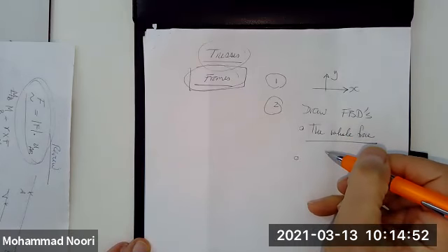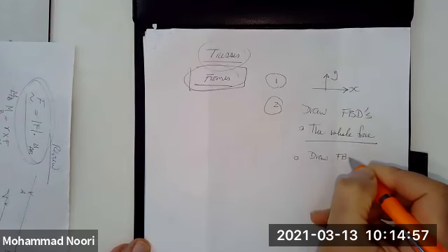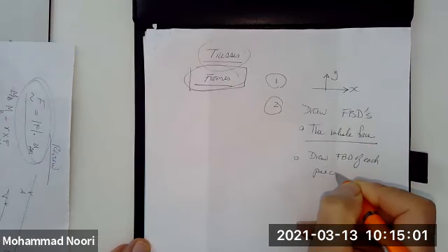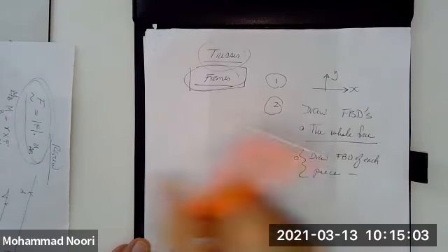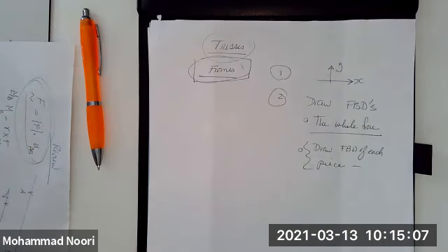Break the structure apart, draw the free body diagram of each piece. Now, in doing so, the most important concept is if two elements, two components are connected, and of course in frames all the connections are pin connections, right?